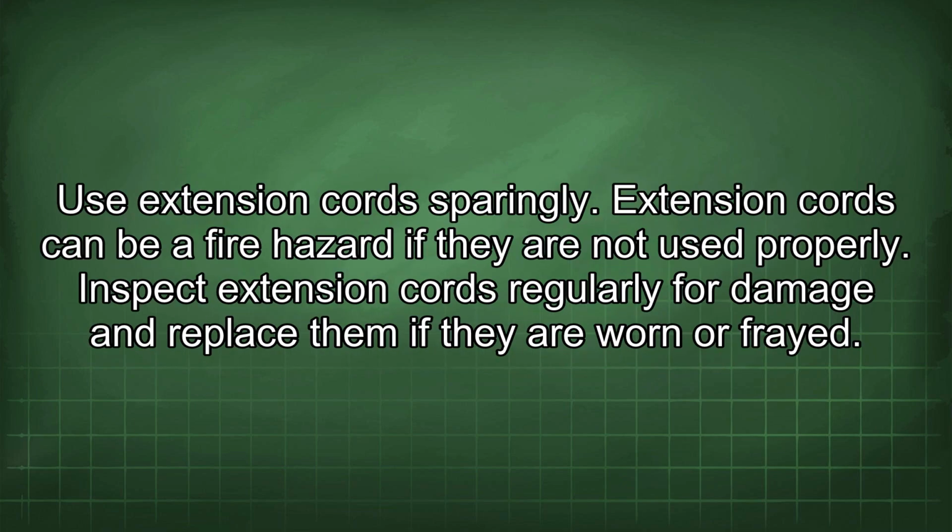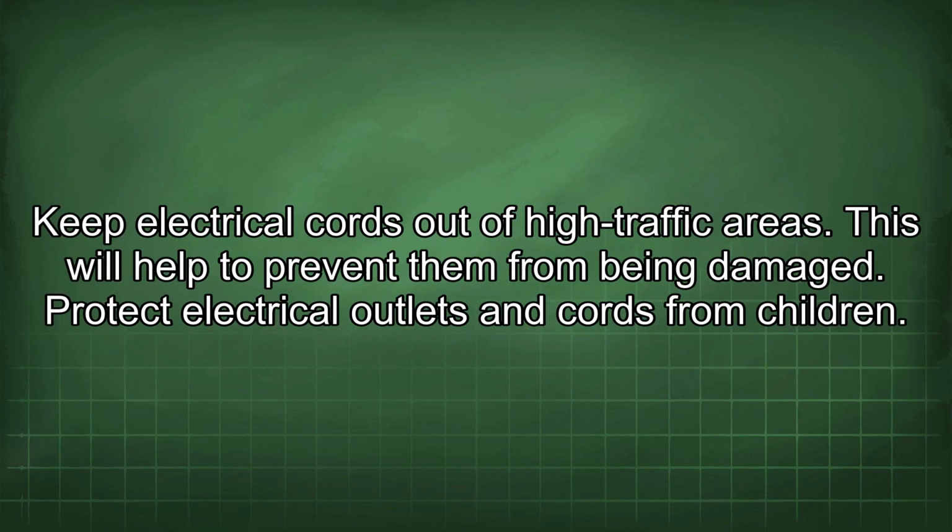Use extension cords sparingly. Extension cords can be a fire hazard if they are not used properly. Inspect extension cords regularly for damage and replace them if they are worn or frayed. Keep electrical cords out of high traffic areas. This will help to prevent them from being damaged.